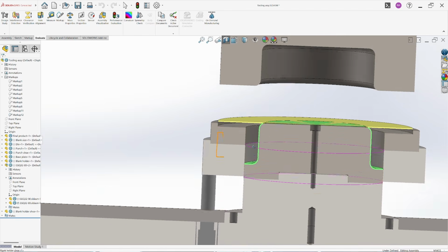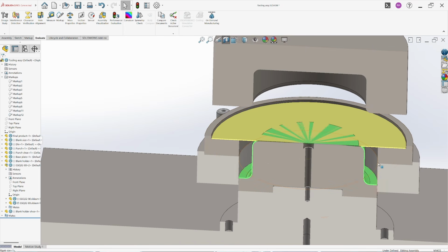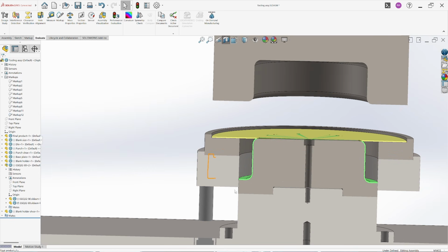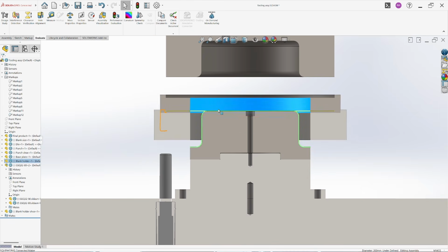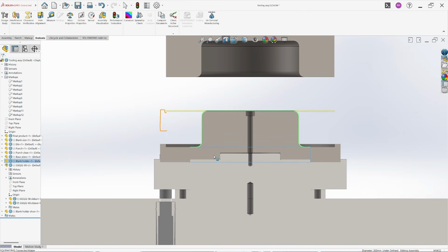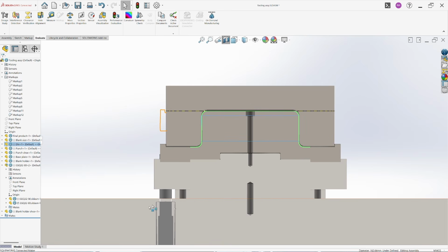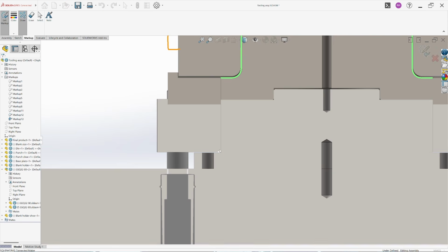Now 300 is the new diameter of our blank holder. So everything is set. Now we can place our sheet into the cavity very perfectly, and then we can deep draw into the die, right? But now here is a new problem. When we reach the end position right here, there is no space. Also it's touching the flange. We need to add a bolt here. There will be a bolt head, something like this, right?